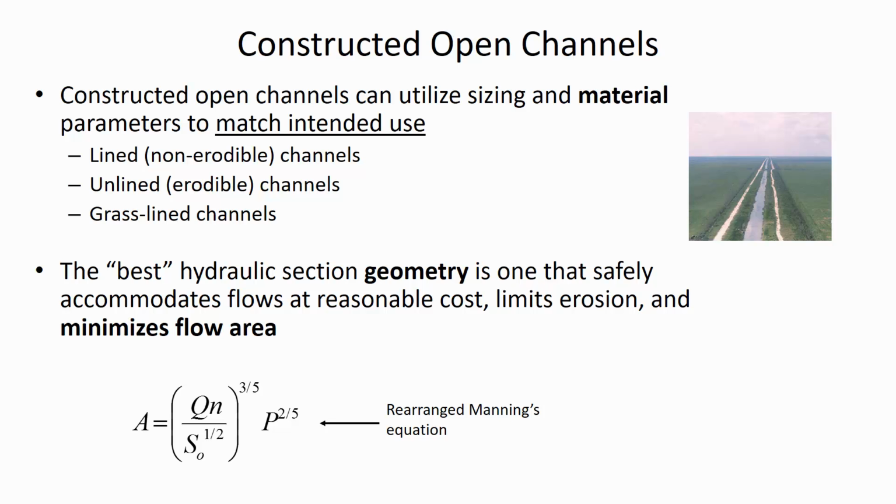So Merritt's Creek, if you've ever been up there, it's just acres and acres of roof and pavement. There's lots and lots of impervious area, where previously there were trees and leaves and vegetation and a lot of things that were absorbing water and promoting infiltration into the ground. When they switched from the natural undisturbed land cover to an impervious surface, that greatly increases the amount of runoff during a storm. So that's an example of how you can indirectly adjust the flow rate that has to be accommodated.